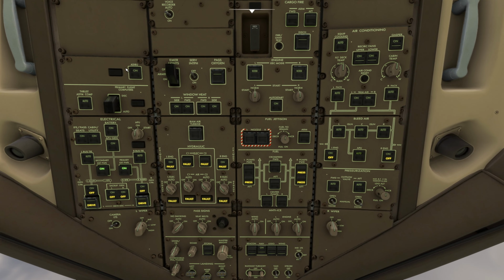On the Boeing, "All aircraft be advised, information Foxtrot now current, QNH 1005." Okay, QNH 1005 is already checked and set. So the philosophy to scan the overhead panel in Boeing is from top to bottom and left to right.